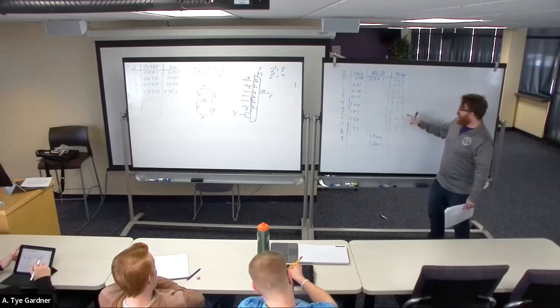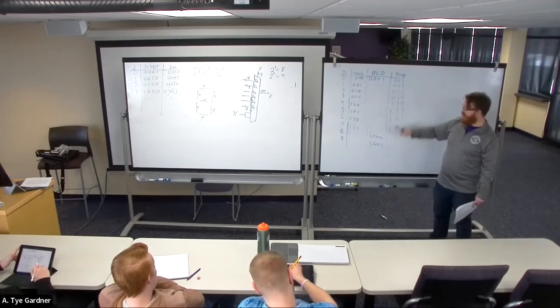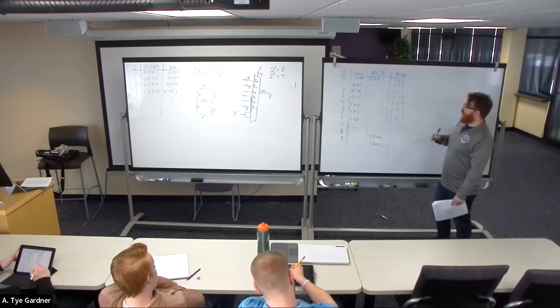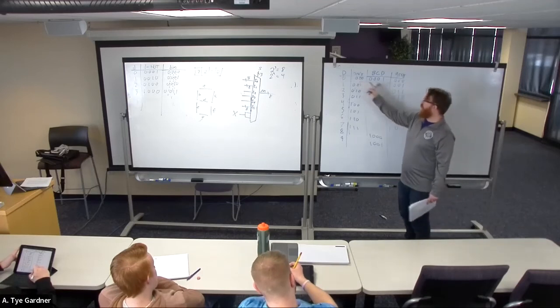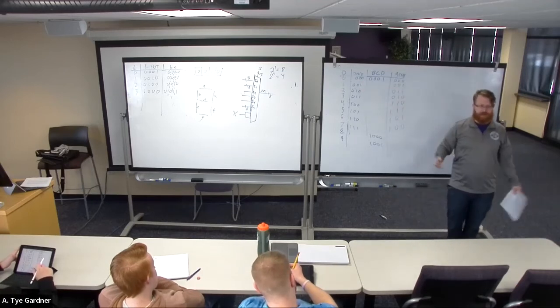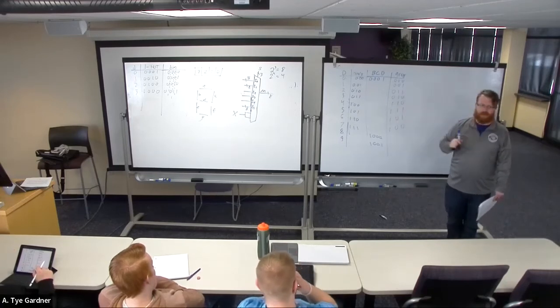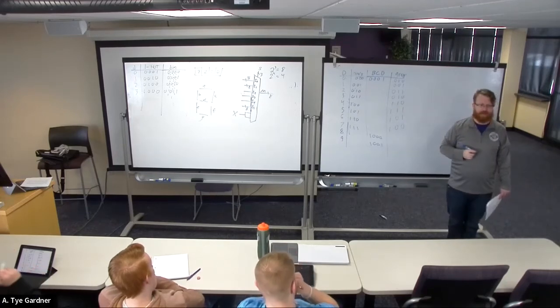Yep. Now that wraps back around, right? Because this and that are only differing by 1 bit. They're logically adjacent. We could do our K-map with these as our inputs. Each one of these zeros is an output. We have 3 circuits. We've built ourselves a binary to gray code encoder.